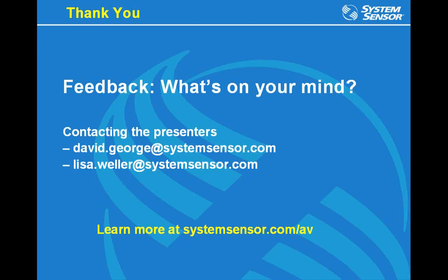I don't know if there are any specific requirements called out in the DOD for male versus female voices. I do know in NFPA, I might have this backwards, but I believe they recommend a male voice outdoors because it will project better. Indoors they look for a female voice because the frequency of female voices is more different from the background or ambient noise. So that's what's called out in NFPA, but I don't believe there's anything called out in the DOD document.